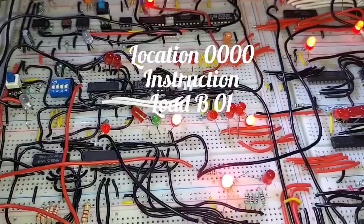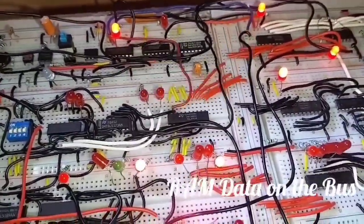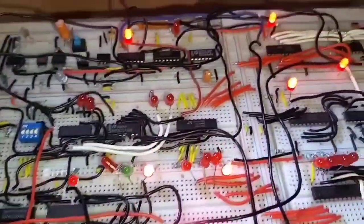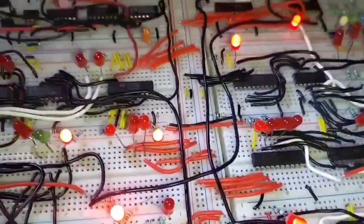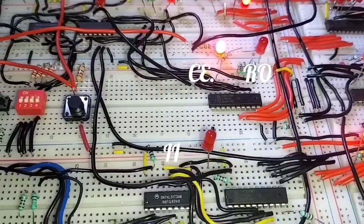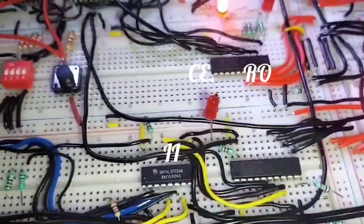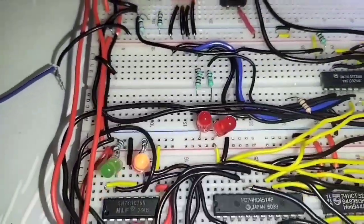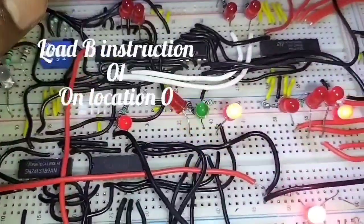The first clock pulse will load the data into the memory address register from the program counter. That is 0. Now RAM out, instruction register in and counter enable are active. The clock pulse will load the RAM content into the instruction register, that is 1. 01 is the load B instruction. You can see.